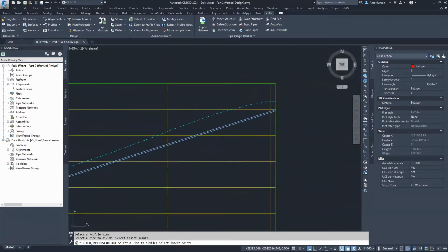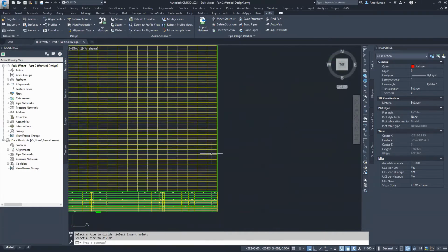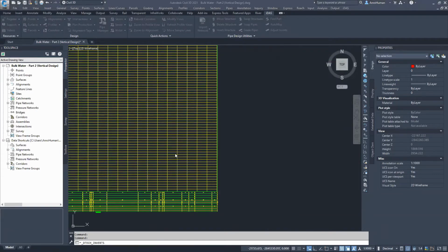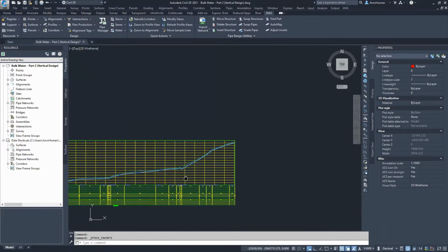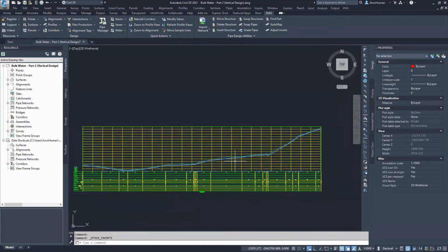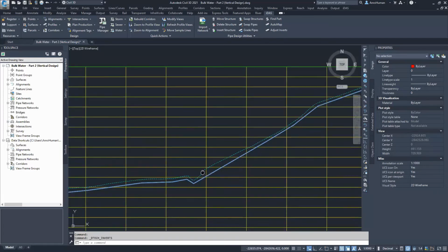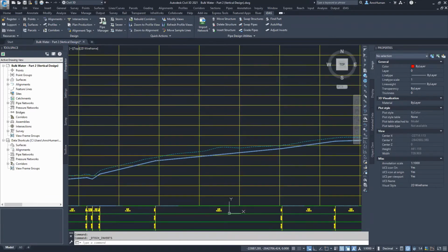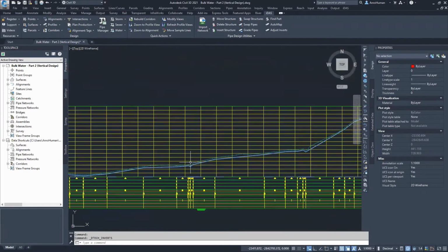There. And there. All right, so we just run that again. Just structure and elevations. Okay. There we go. So that is how you would basically automatically vertically design this network. Although adding in these points, you specifically just select the profile view, select the pipe, and add where you want that node. It will automatically add it in at a certain cover level.